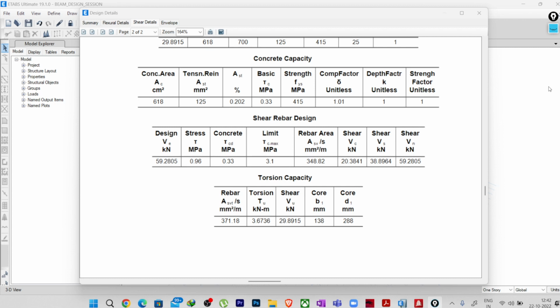But it is not the case. Whenever we draw a beam like this, a frame like this, it is not a fixed beam. These joints are rigid joints, so that's why the analysis results may vary, because here you need to consider the matrix method to solve it and get the actual value of moments, after finding out the displacement, and then you can do the design process as per the code.